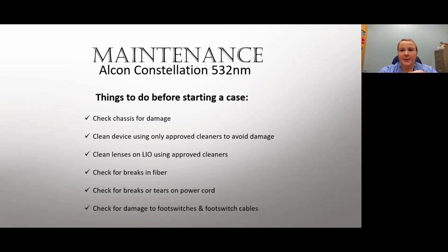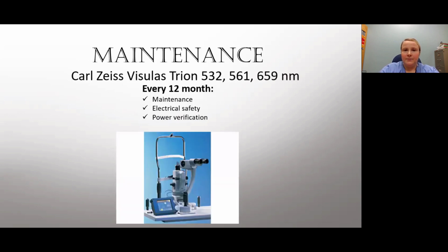Check for breaks or tears on the power cord. Make sure there's no cuts in the insulation, and check for damage to the foot switch and foot switch cables. Just go over the foot switch, make sure there's no cracks. There's normally a shroud over the laser foot switch, make sure that's intact, as well as the foot switch cable, make sure that's connected properly and no cracks or cuts.